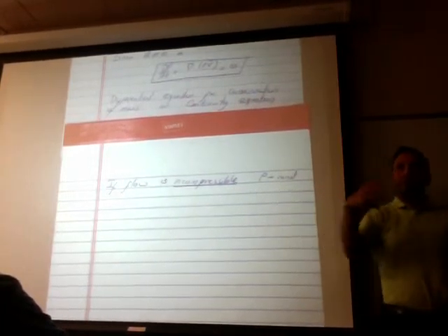But for example, air, which is highly compressible, sometimes can actually flow as an incompressible fluid under certain restrictions and constraints, right? And in fluid mechanics, the limit is the Mach number. If the Mach number is less than 30%, less than 0.3, we can always assume that air flows as an incompressible flow. Beyond 0.3, it flows as a compressible flow, and there are compressibility effects, which change the whole thing dramatically. But anyways, when you can assume that the density is equal to a constant, then this equation